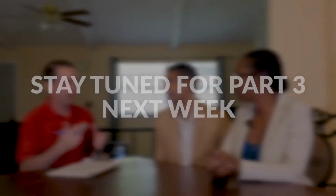So then what I have at all of these locations or these points are these posts or piers where as the house rises and falls, when it gets wet and dry, it can't settle beyond the positions of the piers, okay? That means that we can warranty it for the life of the house.